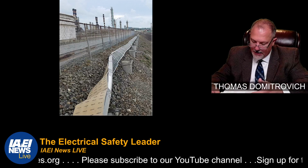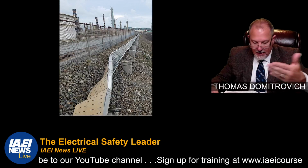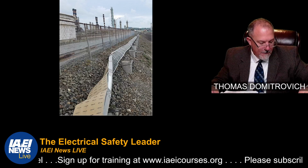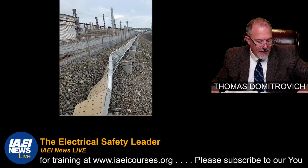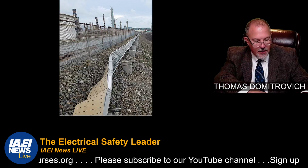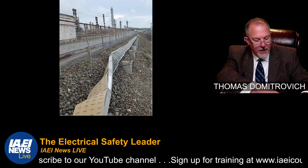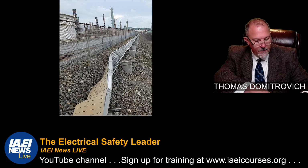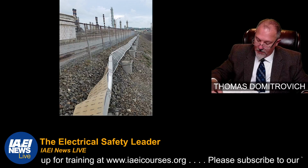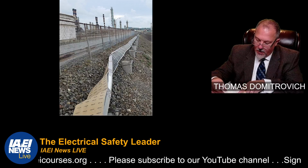Well, we do address splice plates. We address the tubing. Securing and supporting both your cables and your cable trays shall be supported at intervals in accordance with the installation instructions. They talk about the number of cables, conductors that can be placed in there, the ampacity. Individual conductors or multi-conductor cables with entirely non-metallic sheaths shall be permitted to enter enclosures through openings. They tell you how to make those openings. They talk about cable splicing, but they're not going to give you wind loads in here. They'll say strength and rigidity: cable tray shall have suitable strength and rigidity to provide adequate support for all contained wiring.